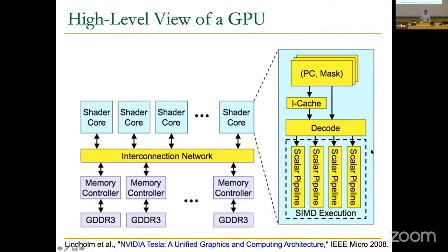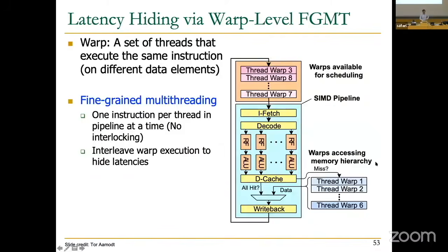That means the hardware warp size is 4. You can execute 4 of these same operations in different pipelines. And that warp goes through the pipeline and eventually gets out, going back to this pool of warps that you can schedule. So what a GPU does today is it schedules these warps into the pipeline, and the pipeline remains very simple.